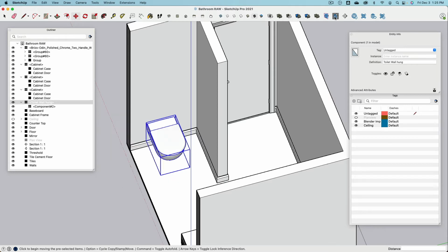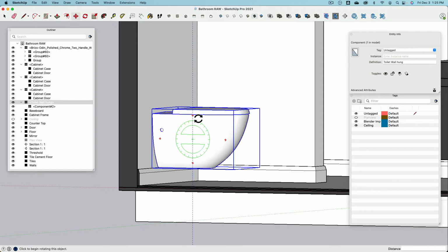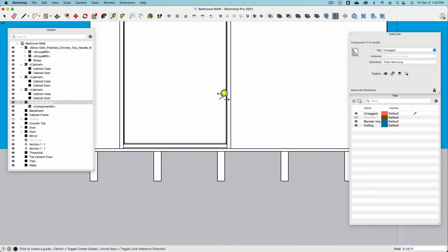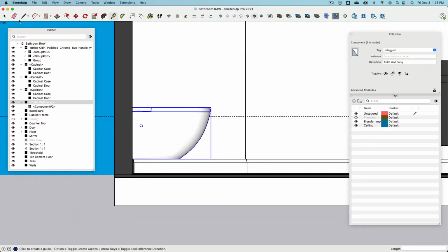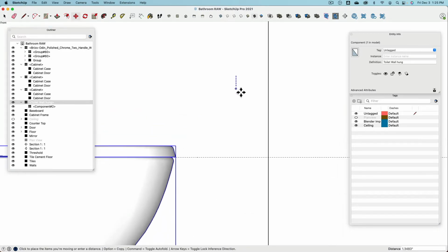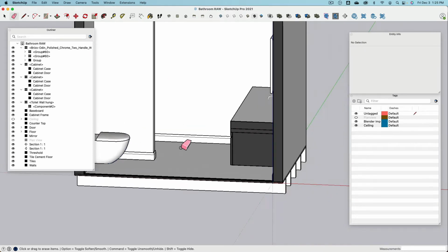Let's turn on the section view again. And this needs to be at 16 inch. I can Google this, you find the dimensions for that. Or whatever standard you have, or if you want this to be for a tall person or a small person. Standards have a plus minus. So there we are. Okay, so it's a tick too high. I can click somewhere else, press the up key and then snap this one down. Let's say there. Beautiful. Okay, really good.